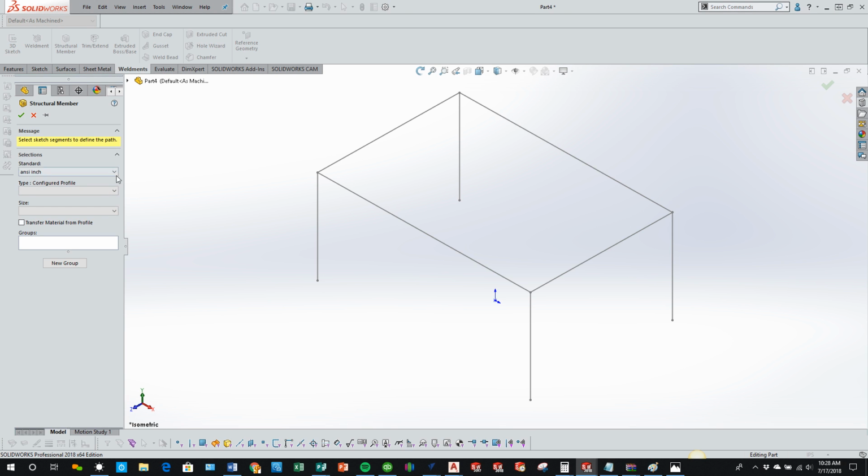So for me, on this application, I'm going to do the wood one. These are custom profiles that I made, and I based it off of lumber that you can purchase at Lowe's or Home Depot or whatever lumber store you go to. I specified a 1x configured, a 2x, and a 4x. I just call them these, and so if I say, hey, I want a 2x, but I want what's known as a 2x4, that's what it's called, but I actually have the true dimensions on it of what an actual 2x4 is. It's a 1.5 by 3.5, give or take.